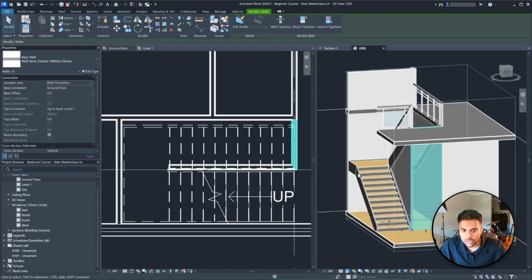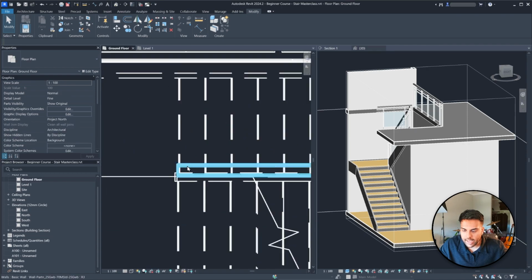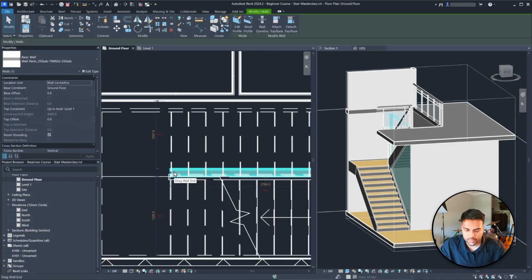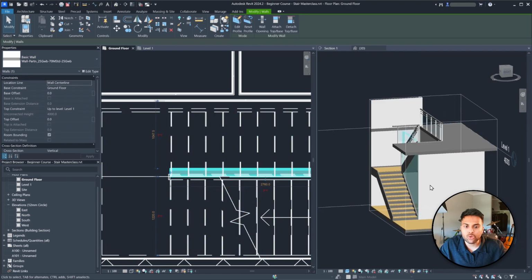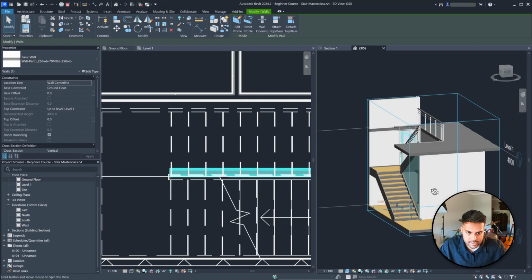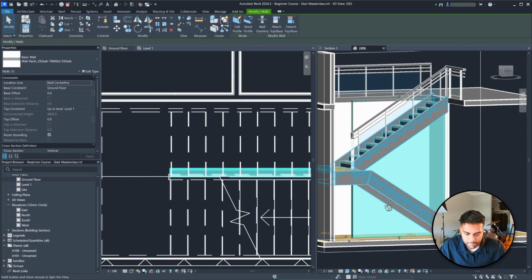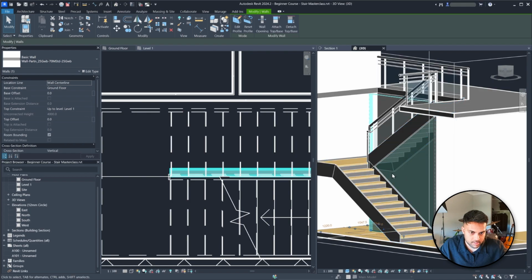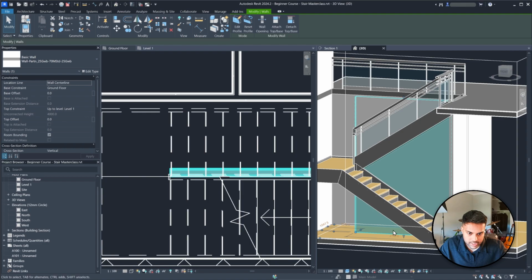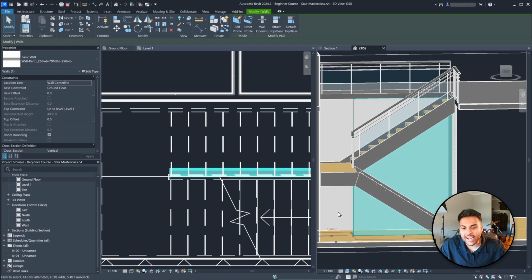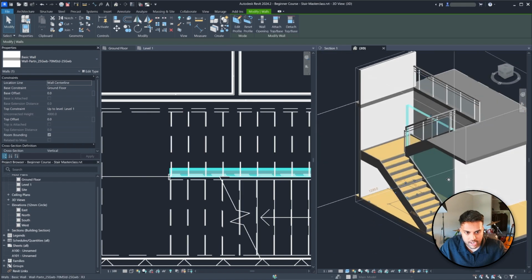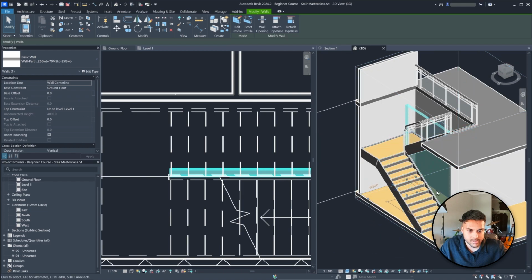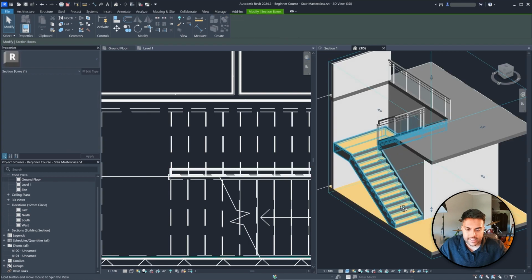An additional thing you can do, if you want to actually use it as a closet, is add an additional wall that spans from here to here, right? And then you would do the exact same thing. You'd put a section there and edit what it looks like so that it just sits below that staircase, right? So then you have a staircase that you can see when you go into the broom closet or whatever, and that wall is going to be attached to the floor, and then you have a back wall over there. I'm not going to add the back wall because I'm not going to add a door in this case because I don't want under stair storage, but that is the idea behind this.